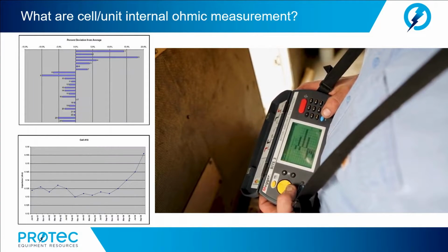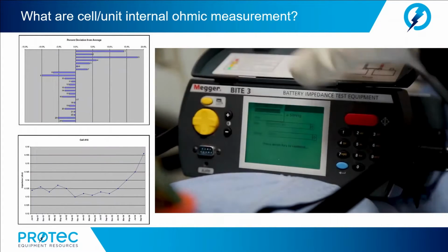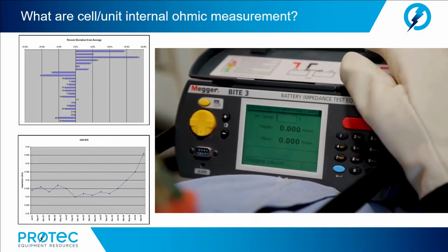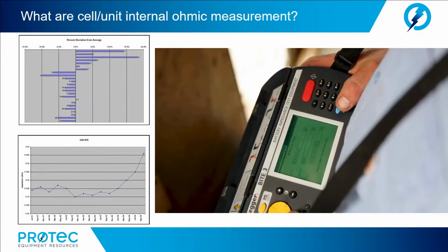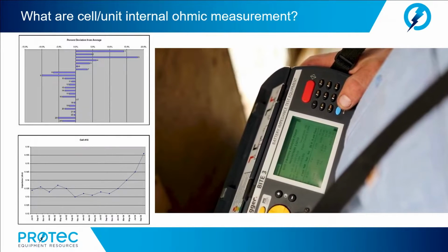By taking this condition-based approach, these owners have eliminated having to perform capacity testing at prescribed intervals to determine if a battery needs to be replaced, and are still able to effectively determine if a station battery can perform as manufactured.